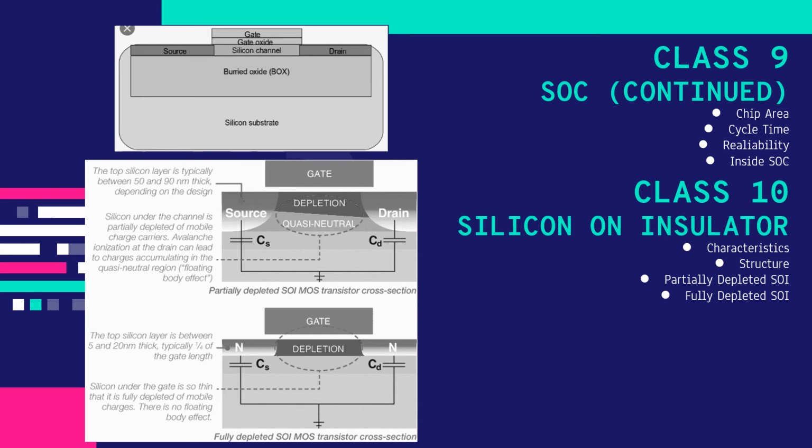We then moved on to reliability, which is related to deep submicron effects. We learned that in order to improve reliability due to a single event, techniques involving voltage scaling and application task mapping can be applied. We also briefly looked over photolithography, etching, and how, because sometimes masking doesn't take place well, task mapping was applied to overcome this.